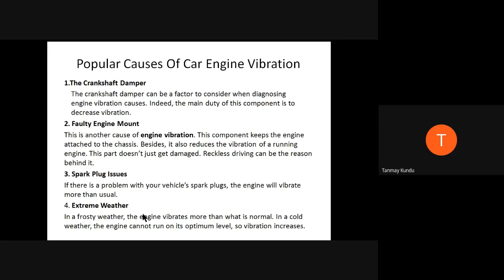So this is the main purpose of the mounting. With the help of this mounting, the engine is attached to the chassis. There is a connection between the chassis and the engine, and this happens through the mounting. If your mounting has some kind of problem, obviously it will be a totally unbalanced situation, and from that, the creation of vibration will occur. Okay.